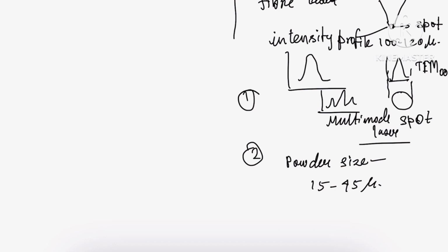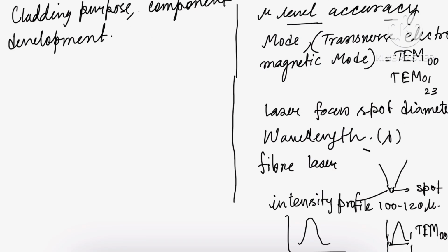material processing applications. In the low power, achieving a single mode or a one peak Gaussian laser beam is easier, while DED deals with higher power, sometimes in kilowatt. In that case, the lasers are multimode due to the fiber coupling of multiple single emitters or single mode lasers, which deteriorates the property of the laser and the printing accuracy. However, you can achieve single mode laser with a better optical arrangement. So that's another thing which is important in case of DED.